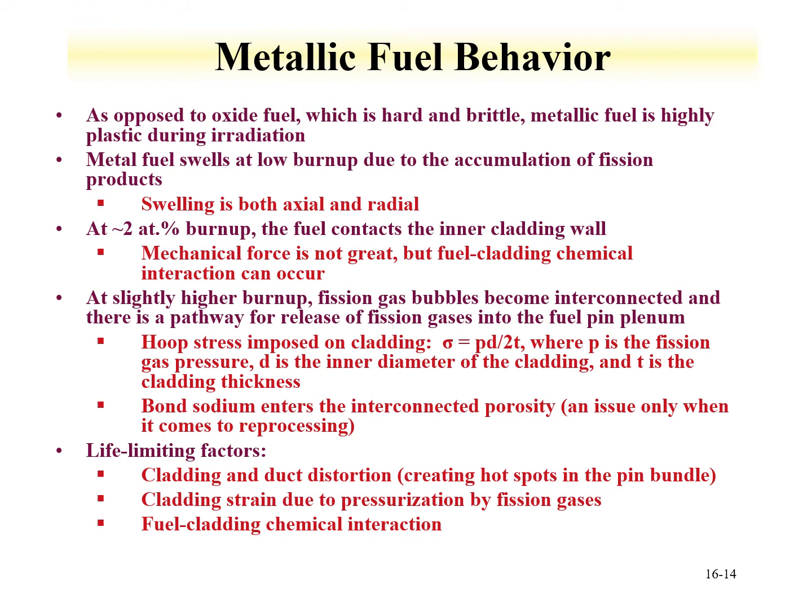And some of the limiting lifetime factors for metallic fuel are the cladding and duct distortion. So in other words, as the fuel keeps swelling and if it keeps bending into the cladding material, this is a not desirable property and one would have to change out the fuel. And any strain due to pressurization of the cladding due to the fission gases and this fuel chemical cladding interactions.